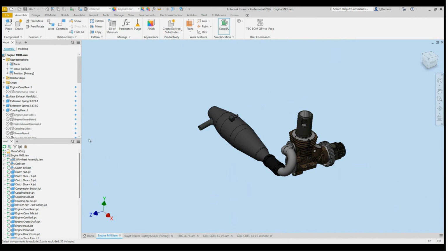And what I'm creating, this is my output. I'm taking this assembly file, and I'm going to create a new part file. And I'm going to use a particular template. And the name always gives it a suffix of _1, but I can give the file name anything that I want. It's going to create an IPT file. And then that's the path it's going to be in.